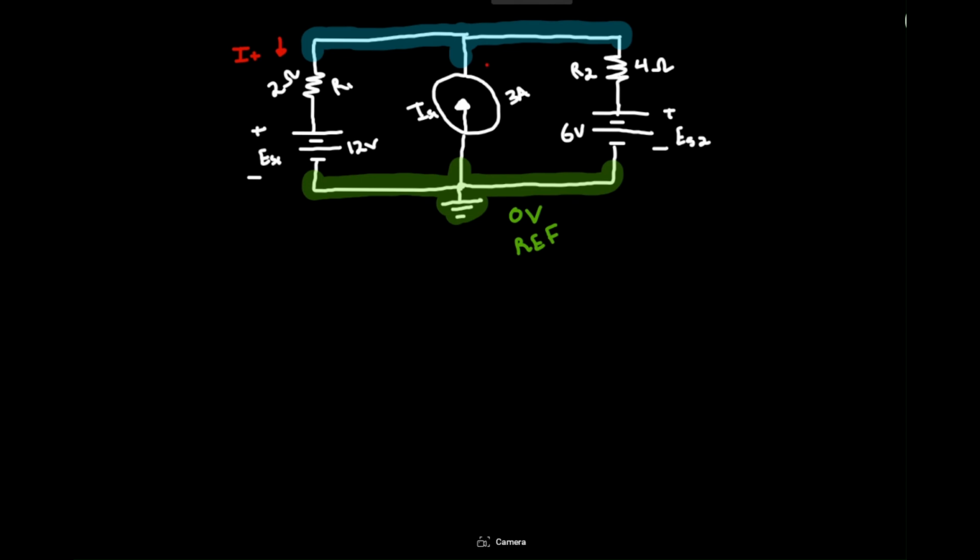So in this case, I source 1 is gonna be negative, entering that node. And then this one, we can assume it's leaving just to make our life easier. That current is positive. Okay, now we have fully labeled the circuit. I'm just calling this VA. Now we can start solving for voltage VA, through doing KCL and finding the current on that.